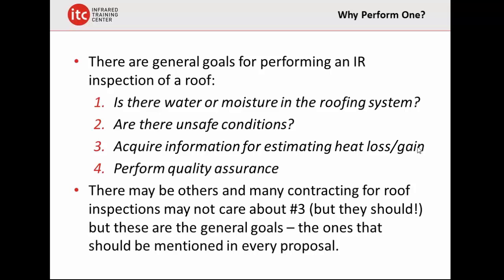This would not be for an inexpensive camera. This would be more for a higher performance camera. It probably involves some software, and actually converting that to BTUs per hour. But it certainly could be done with a little bit of science involved. I've never really thought about doing that measurement, but you could estimate or measure the R value of a roof. When you measure R value, it's usually a 24 or 48 hour test because there are so many variabilities, particularly with the wind. So it's not an instantaneous measurement, but yeah, it could be done.